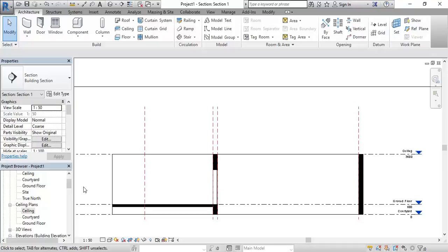And in a room like this, for example, the sill of the windows is over 1 metre high, so the windows wouldn't come up in your floor plan either. You just see wall. So normally make it higher than 1 metre. 1500 is good. So the ground floor has a cut plane of 1500, which would be about here, going through the door and all of these walls, cutting through and looking down. Now a ceiling plan is basically the same, except that it cuts through and it looks up.